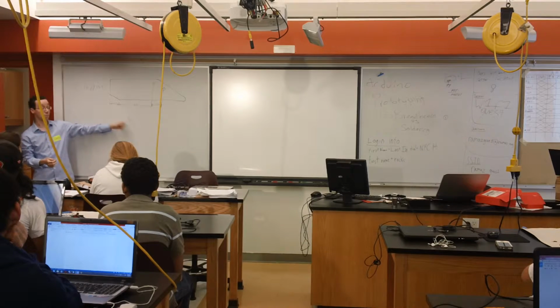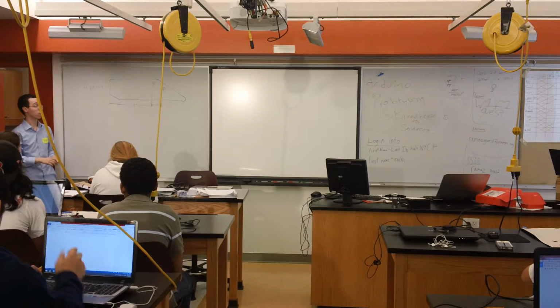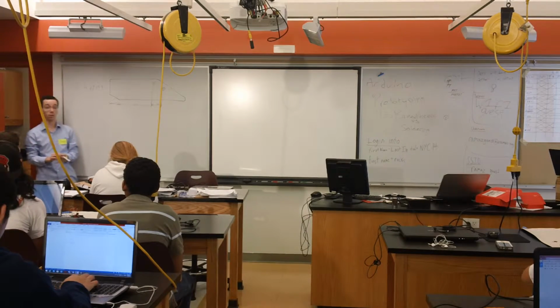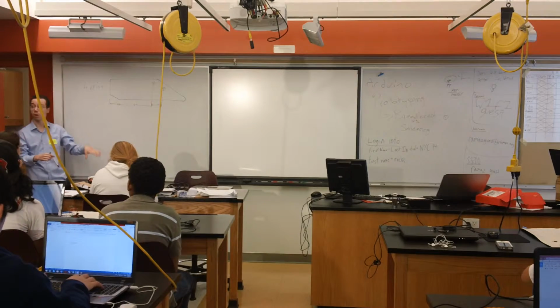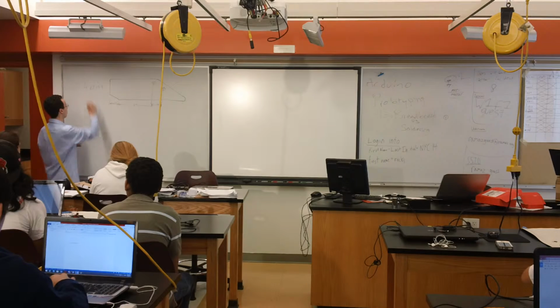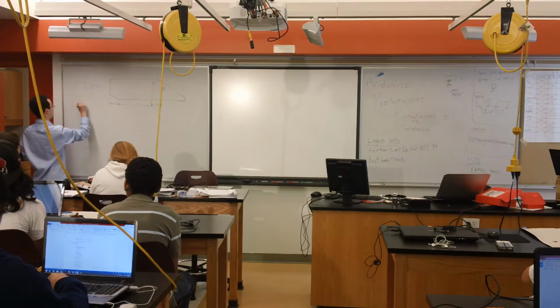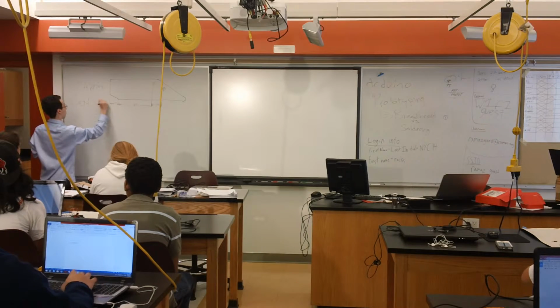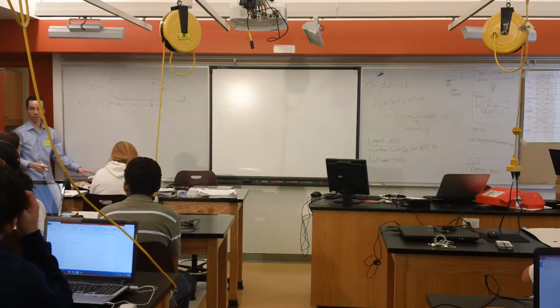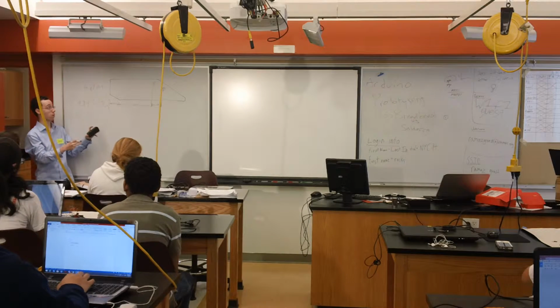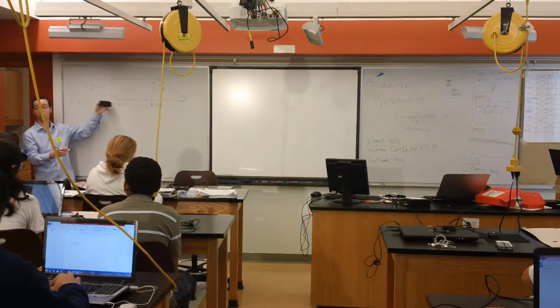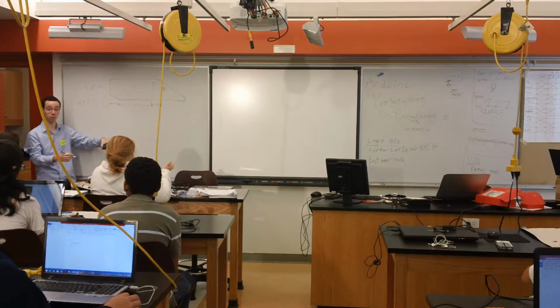This is nice and human readable in a lot of cases, but if you're a machinist, especially if you're using a milling machine, a CNC, and you want to know exactly where every part is, another way to do it is what we call datum dimensioning, where I set every feature and I show where it is relative to this point, not relative to the last feature that I dimensioned.